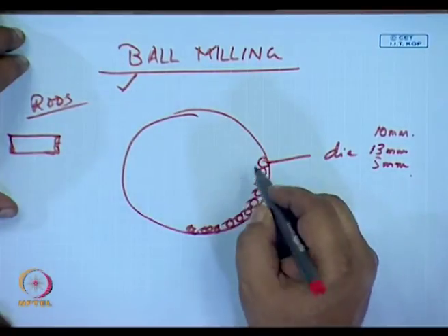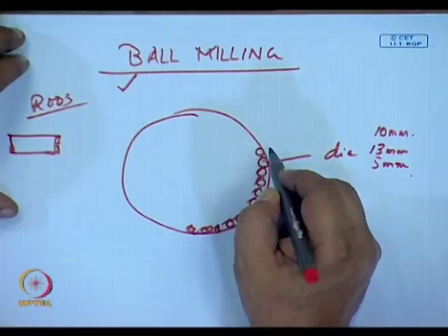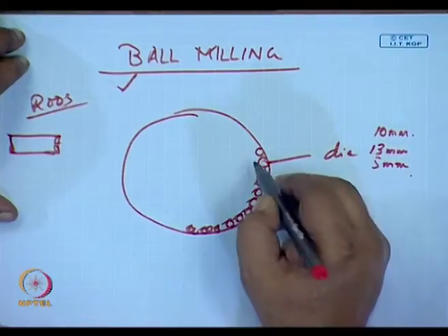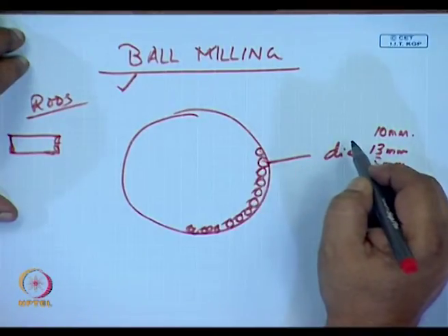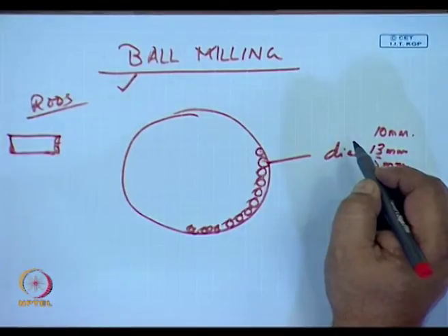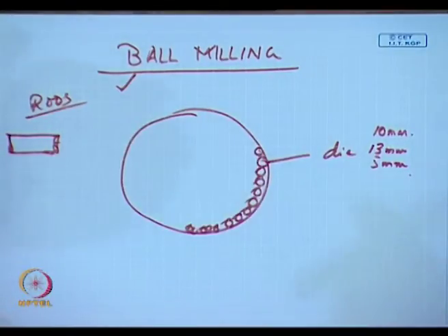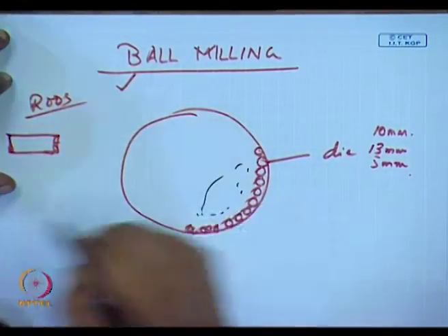So, what is done in this ball mill? They are about 1/3 filled with balls. These balls can be steel balls, these rods can be steel rods. There are porcelain balls for soft material. Say you want to grind talc, a soft powder, use porcelain which is harder than talc. But if you want to grind sand, you have to use steel balls. It depends on the hardness of the raw material. And it is also filled up with the ceramic powder.